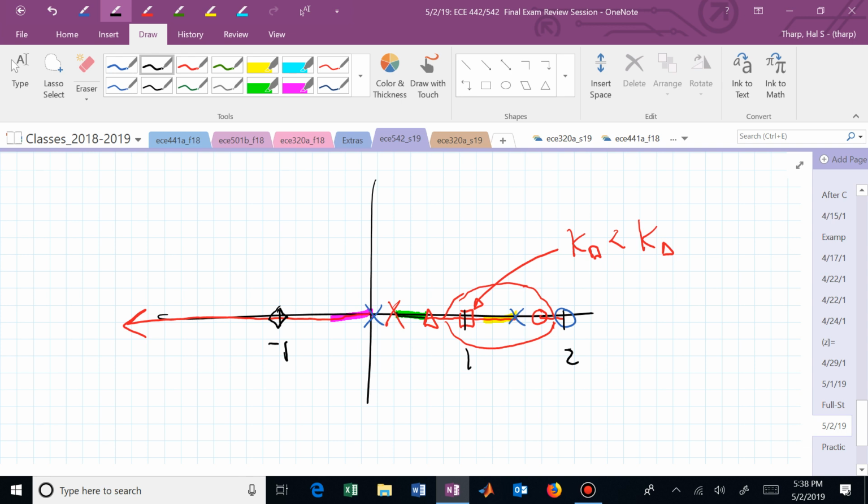And how could you determine, well, you also have clouds. Those are going to go outside the unit circle eventually, aren't they? And so K cloud might be less than K diamond. And so your range of K for stability might be influenced by box and cloud versus box and diamond. But you now have those concepts or ideas to help you process. Yes?